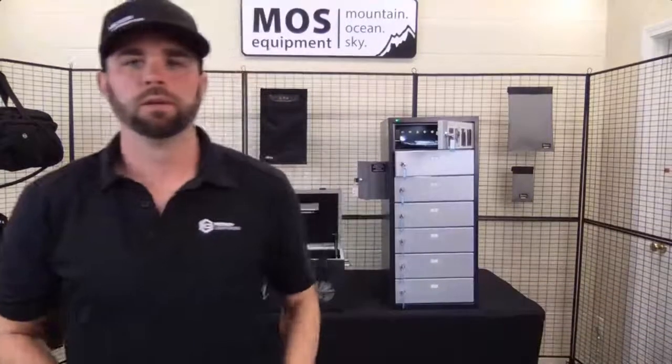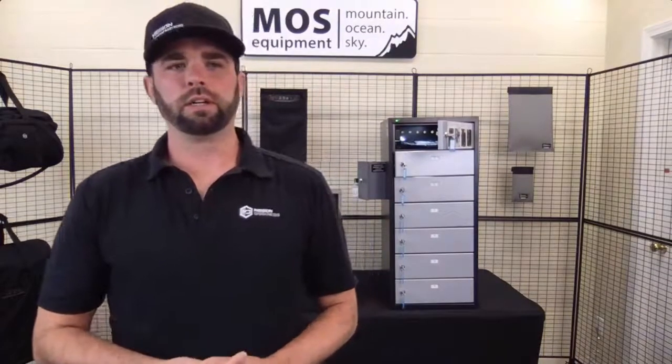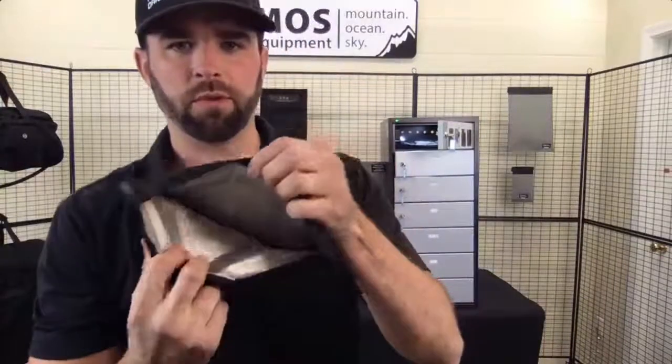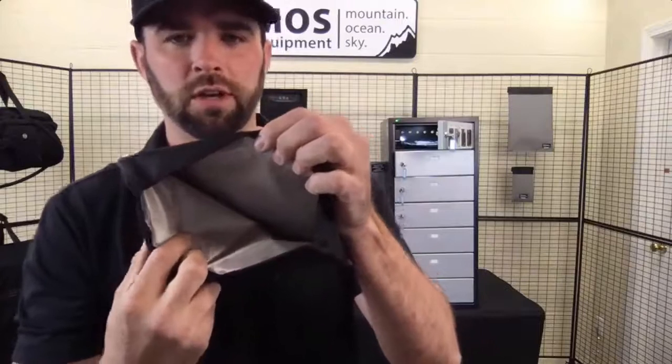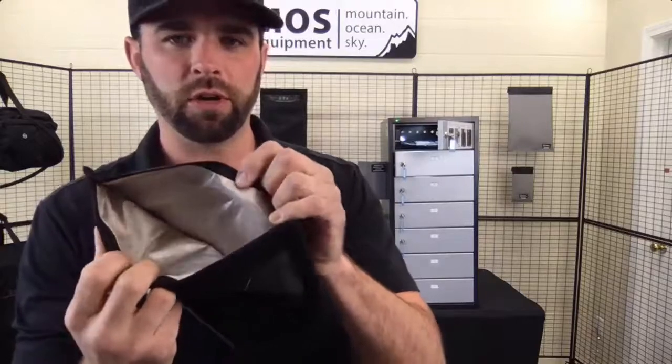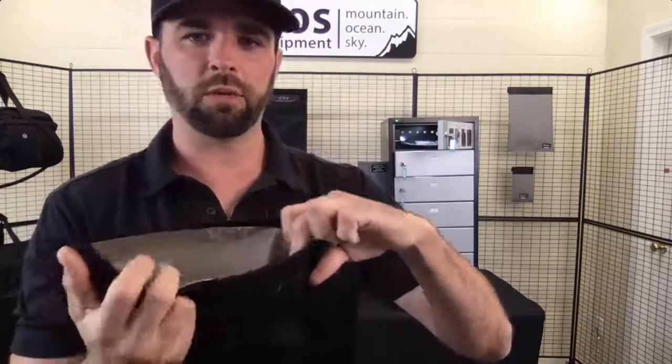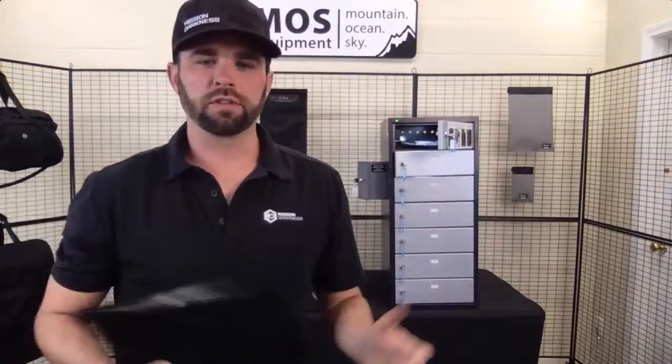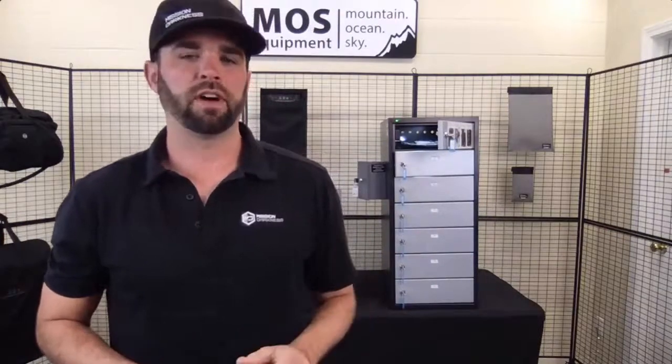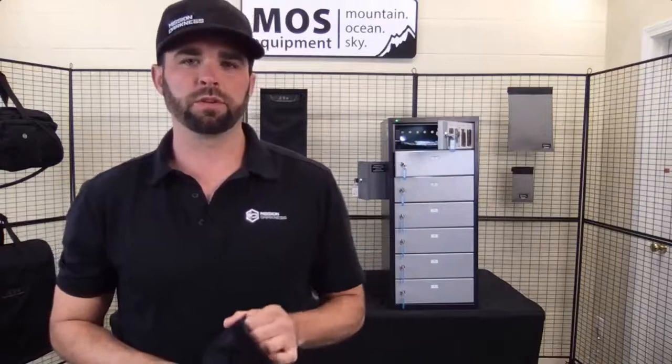Okay. Are there any options for disposable, one-time use Faraday bags? We don't offer that. The problem is, to get a really good Faraday enclosure, like this bag for example, there are 2 layers of the shielding material on both sides. This material is not cheap. It's metallic fabric, customized for these frequencies, and we build this bag in a certain way so that it's going to block well. A lot of the products out there claim to block all signals, and they're $5 or 50 cents, disposable. They're just not going to work as well.